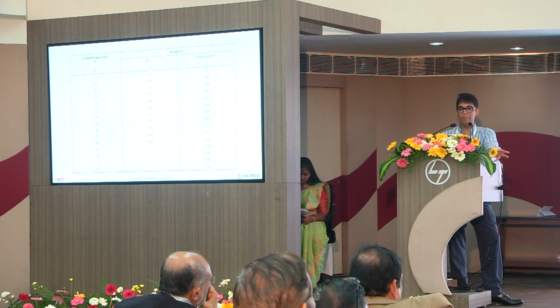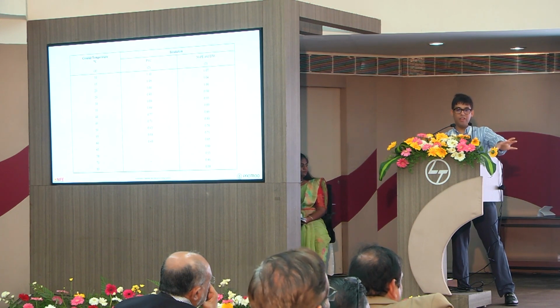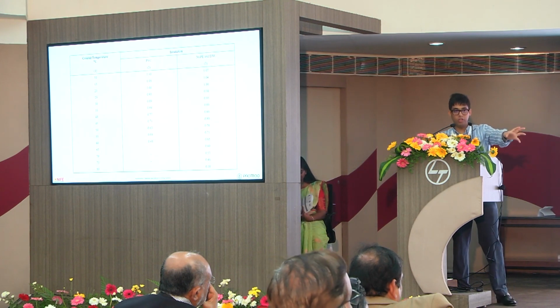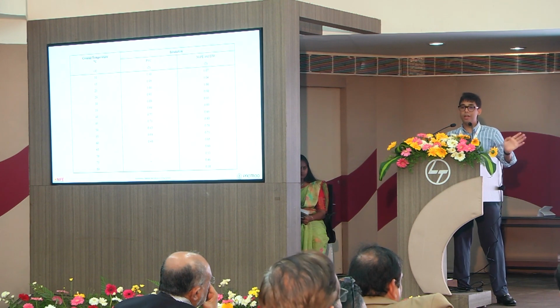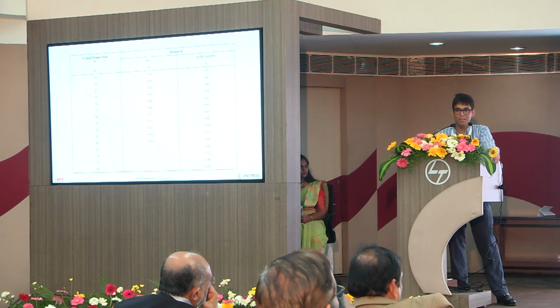Now, ground temperature. Come on, this one is really easy. By the way, even though it is a 90-degree cable, we will assume that we can only use the current carrying capacity to 70 degrees because we don't know the equipment limiting temperature. So then we've got PVC. This is a really easy one. I do expect somebody to give an answer for this, please.